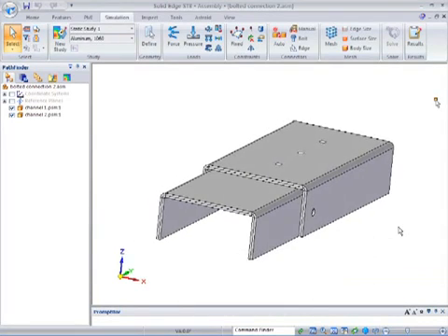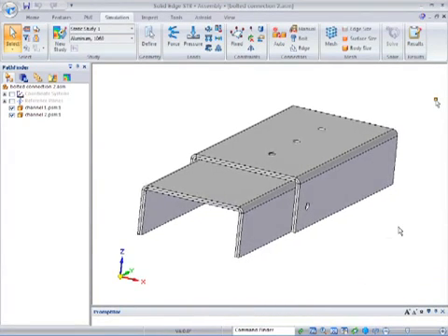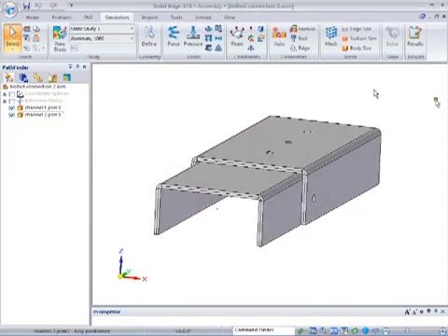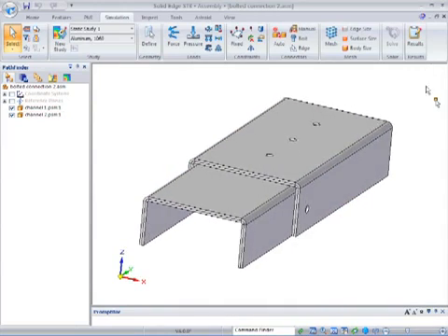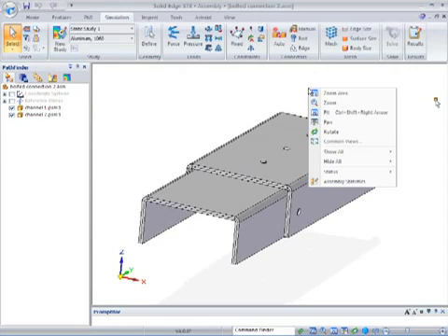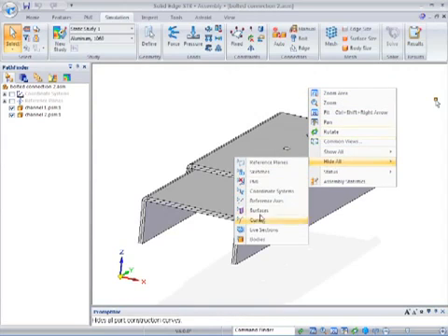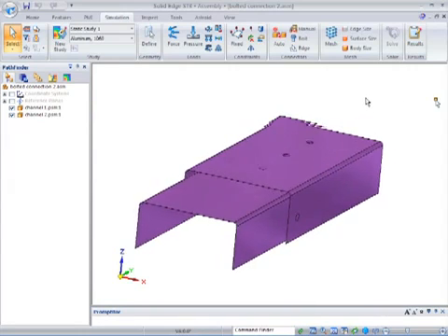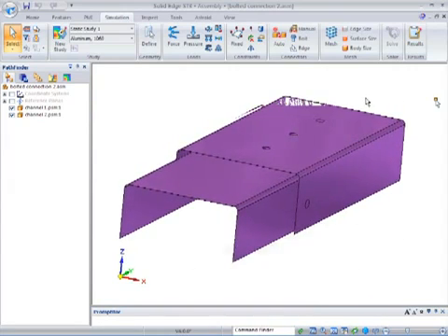In this assembly, you have two components. They're sheet metal parts that are basically bolted together on each side as well as across the top with 3 holes. Now, using Solid Edge simulation, we can certainly create an analysis between a solid and surfaces, or just use the surfaces. And in this case, I've got 2 mid-plane surfaces representing these parts. So I'm basically going to hide the bodies of these parts and just work directly with the surfaces.